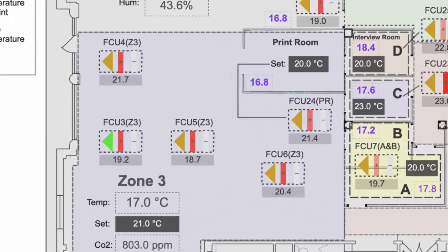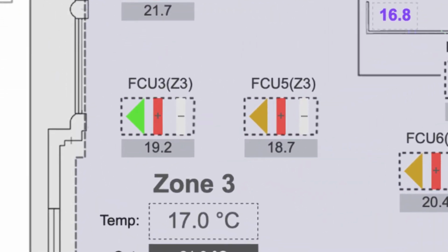The graphical overlay is dynamic. Each fan is depicted by a triangle. This changes color depending on its current operating speed. Each heating coil is represented by a red icon. This is also dynamic. The coil is grayed out if it is off, or displays deepening shades of red depending on the demand level, 100% being bright red. The cooling coils display in the same way but in blue.